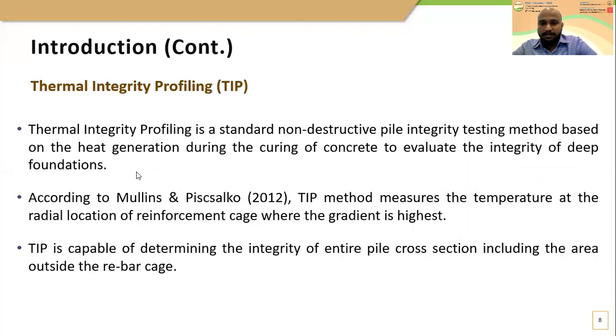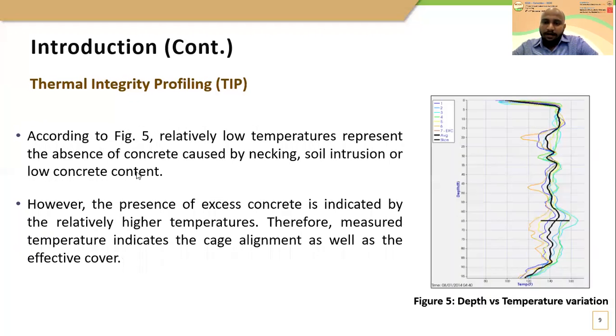Moving on to the introduction to thermal integrity profiling. TIP is also a standard non-destructive pile integrity testing method based on the generation of heat of concrete during the curing process. It generally measures the temperature at the radial locations of the rebar cage with higher gradients. As shown in the figure, relatively low temperature indicates the absence of concrete and vice versa. Also, the measured temperature indicates the alignment of the rebar cage and the effective cover.